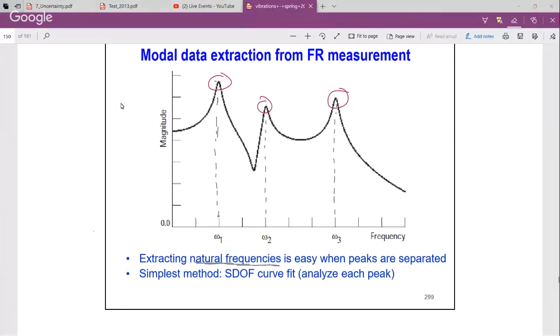All right, so that's logarithmic. Now, we're not going to use logarithmic units in here. Controls do. Controls use logs like that. For linear units, not decibel or logarithmic units, the half power point is defined as the magnitude times 0.707.